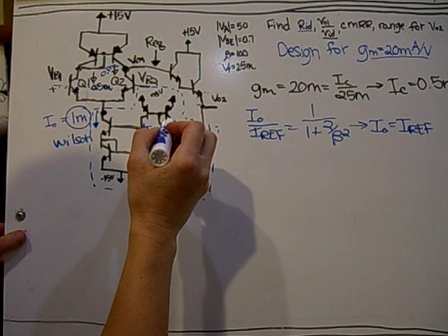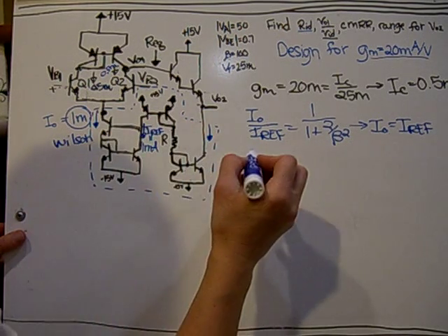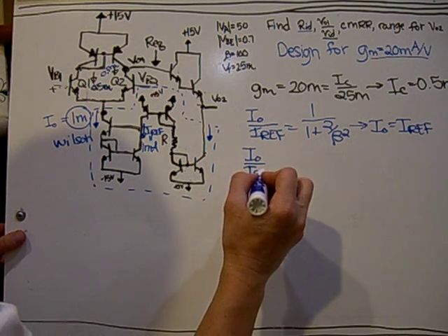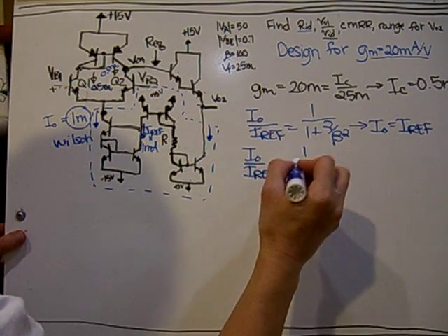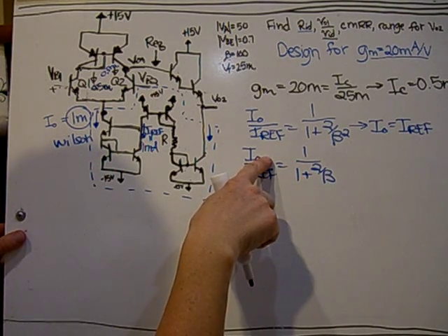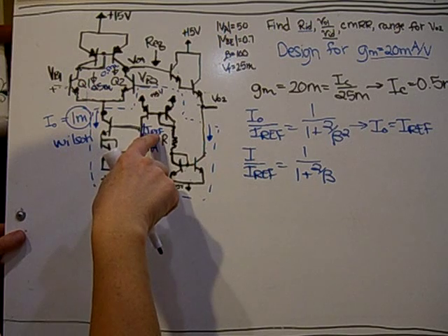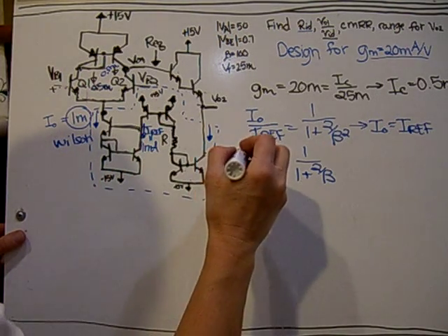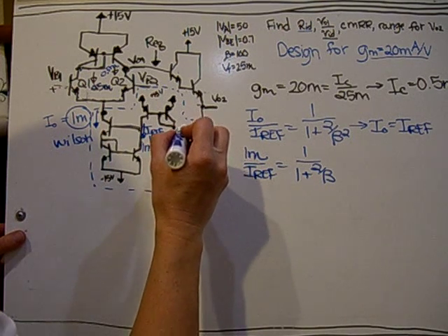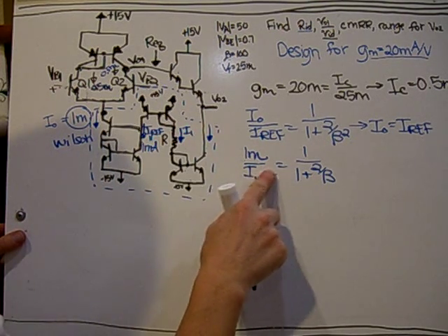And I know it's being reflected here. Again, it's a BJT, and it's a simple current mirror. So the simple current mirror is 1 over 2 times beta. In this case, I naught is this current of 1 milli. And we want to know this current now. I'll call it I1, which will be here.